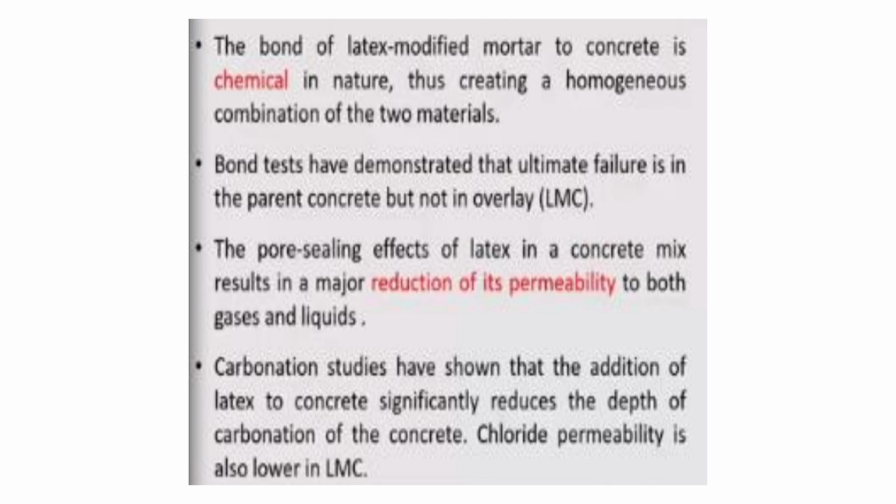Carbonation studies have shown that the addition of latex to concrete significantly reduces the depth of carbonation of the concrete. Chloride permeability is also lower in case of LMC. So the depth of carbonation is reduced when latex is added, and chloride permeability is also lower in case of LMC.